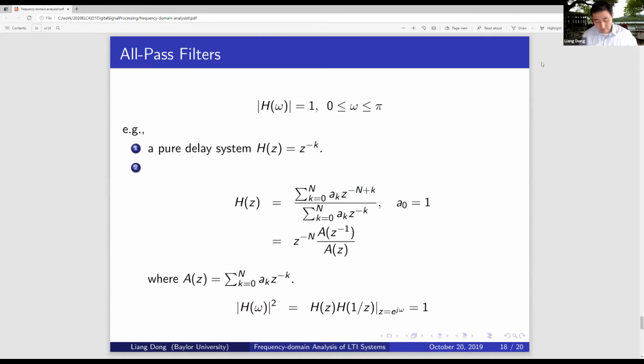For this digital resonator, in practice, the frequency is a little off. We know that's due to the pole. The other issue we haven't looked at mathematically is the phase. It's a nonlinear phase, and nonlinear phase is something that we don't like. So we want to compensate for the phase nonlinearity.